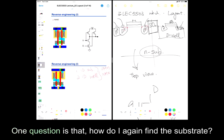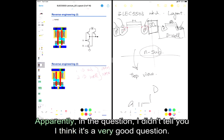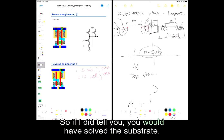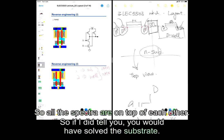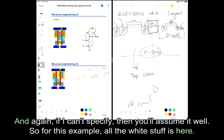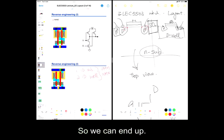One question is how do I identify the substrate? I think it's a very good question. Apparently in the question, I didn't tell you what substrate it is. If I didn't tell you, you will assume it's a P substrate. So all the background color is your P. For this example, all the white stuff is your P. And again, if I didn't specify, then you assume the well will be an N well.